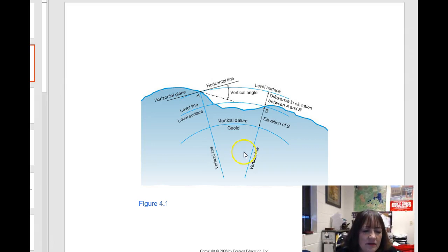The elevation of a city or the elevation of a place does not change based on time or based on the fact that sea level rises or falls. And that's actually the meaning of the word datum. Datum just means something that you refer to. So the idea of mean sea level was created by the National Oceanic and Atmospheric Administration, or NOAA, and it was just created by a series of buoys that are put out into the ocean and into seas to establish how much it varies, and then a number was arrived at, and that fixed starting point is the 0 on our scale of operation.